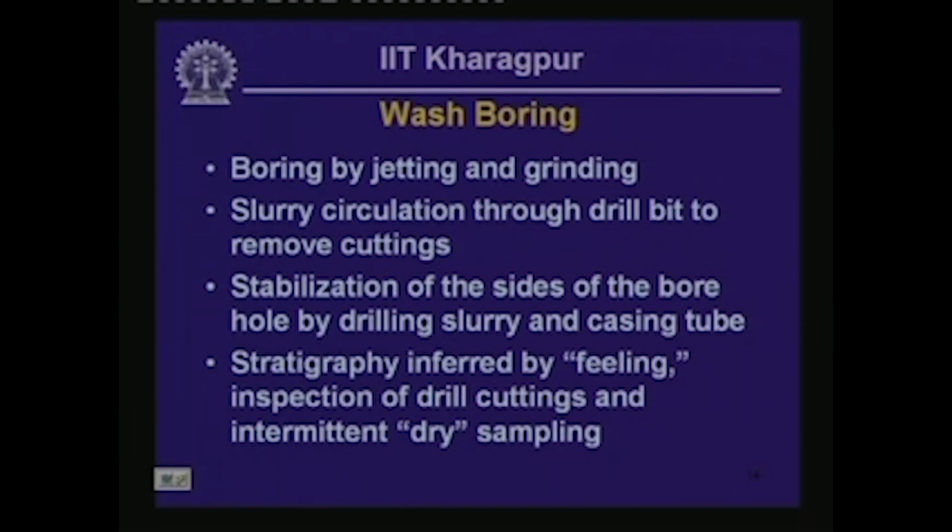At the same time, a water jet or a jet of drilling slurry, which is water mixed with some stabilization fluid, typically bentonite, is pumped through the tip of the drill bit, and that imparts a scouring action.